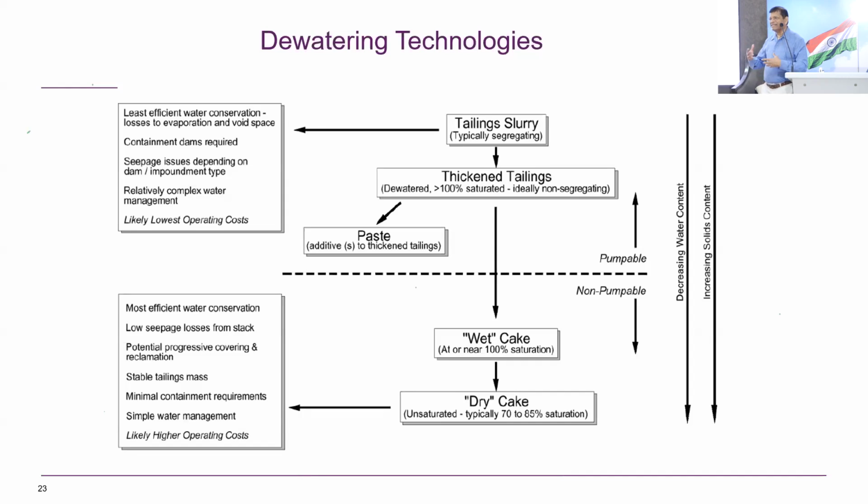Again, there is no guarantee that it will be fully successful. We are doing some experiments, and on some sites it is successful, but in general we still have to look into that particular site and what is going on. But if you identify the conditions, you take preventive measures, put in some berms, and the main thing is to monitor it.